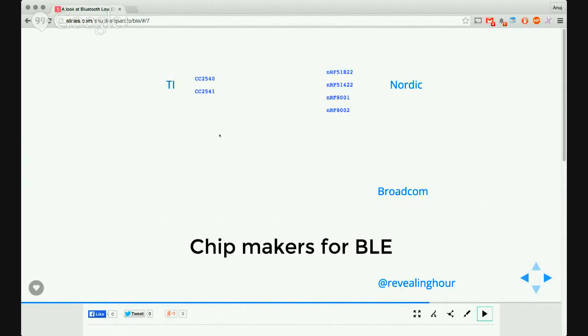Broadcom entered the whole Bluetooth low energy segment quite late as compared to Texas and Nordic. So they have plenty of modules which mix the older Bluetooth with the Bluetooth low energy. But these two are the only ones which are single band, and they have purely Bluetooth low energy support. They built a small sensor which has 5 environmental sensors and used the BCM20737S to create a small module for it. We'll go into the details in the next slide.